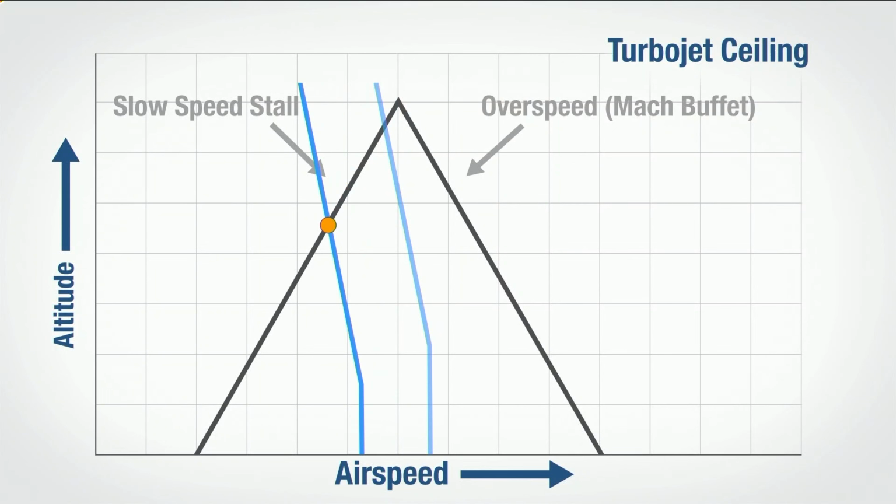The key thing there is to descend. You really want to maintain your airspeed, but to get the aircraft out of coffin corner, the best solution is to descend. Because let's go back to that coffin corner slide. I'm just going to rewind this all the way to the beginning.